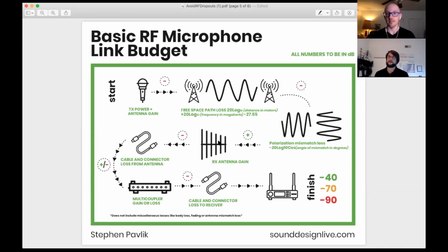It can happen. We don't need to dive into that, but okay, we're pretty much always going to have positive gain from an antenna, and that's passive gain. As we talked about antenna patterns, I'll use this as an example again. This is going to be basically our cardioid because we're not radiating this direction or behind it. That radiation that is coming out this way is forced forward. And so that is our passive gain, which is about 7 dBi. So at that point, we can use this little green plus here to add 7 to our link budget.